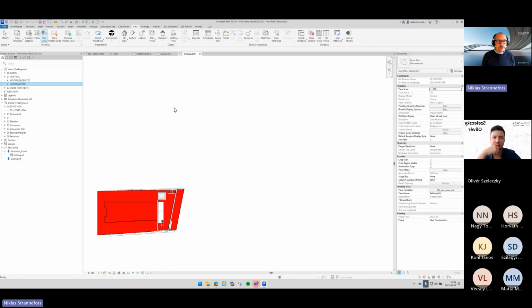The unconnected view is going to show if a component has a dash, a line, or no value at all in the parameter called NVGUID, Naviate Global Unique ID. So it's going to show us if we try to automatically connect things and it fails, we can see which objects they are. And if we manually place something, we will see those as well. Everything that is connected will not be visible. So we can quickly go through and check those that are not connected to a component. We fix it. But that's kind of what those 2 are.